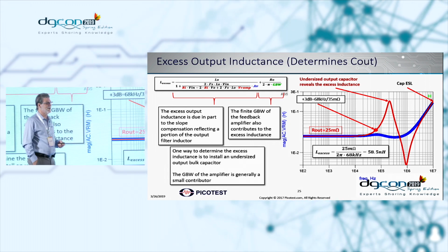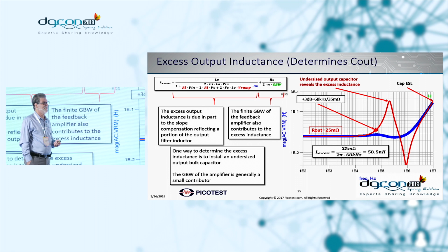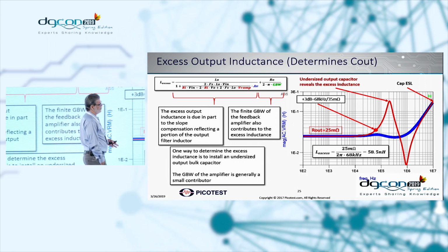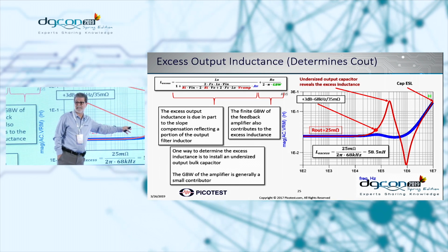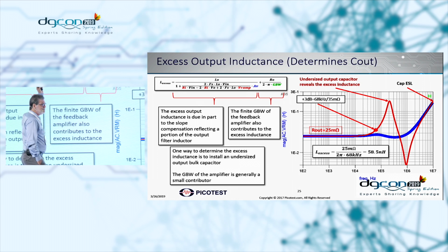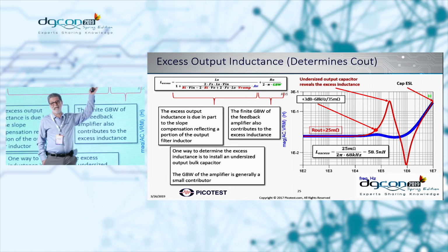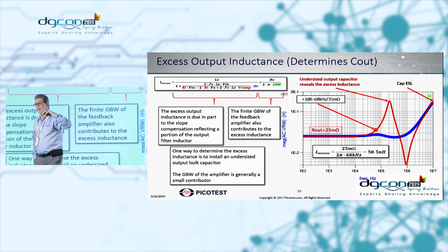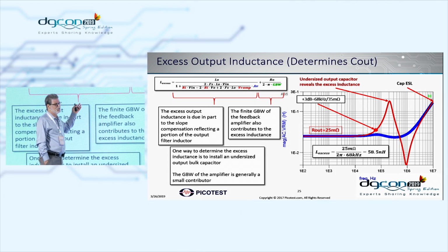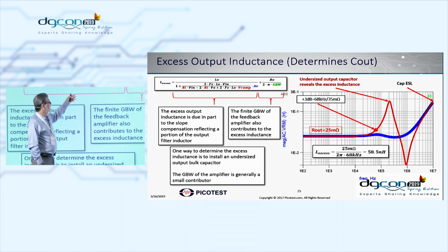Of course, they needed to find a place to put 25,000 microfarads per pin, and that was a little bit troubling. So you only get one other choice, and that is figure out how to drive the inductance down. How do you drive the inductance down? It's right here. Anybody that's interested, I actually did do a paper on it a few years ago in gigahertz bandwidth regulators. And why it is that everybody's so interested in gigahertz bandwidth, it's because the capacitors go to 0.